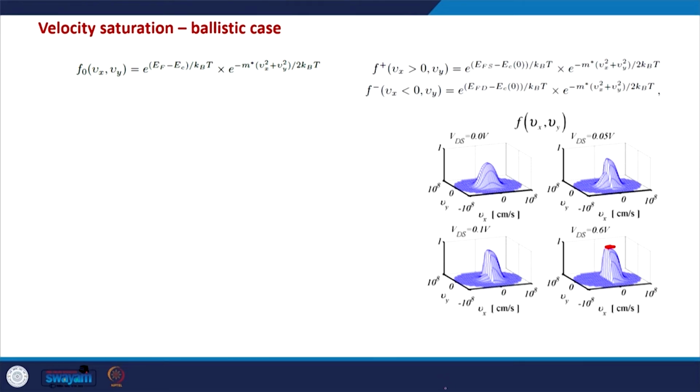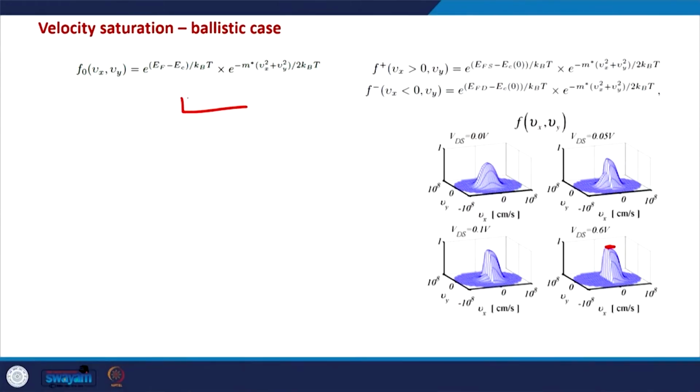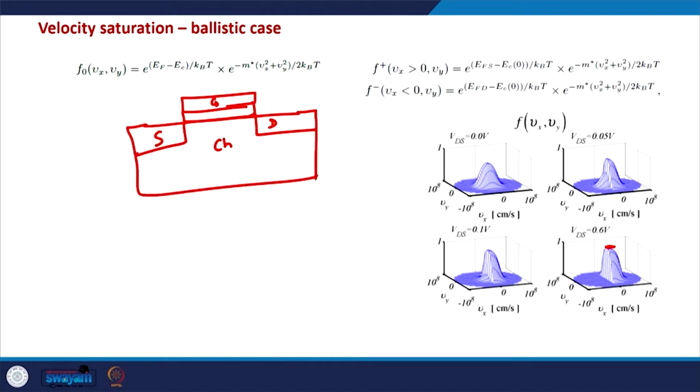And the answer to this actually goes back to the design of the MOSFET. In the MOSFET, generally what happens is that we have a gate terminal, we have an oxide, and below the oxide we have the source, the drain, and the channel region. So this is how the MOSFET looks. We apply a certain gate voltage. As soon as a gate voltage is applied, if we apply a positive gate voltage, we can say that there is a positive charge accumulated on the gate terminal. And generally the channel charge, the negative charge that is induced in the channel because of this positive voltage applied on the gate terminal, depends mostly on the gate voltage